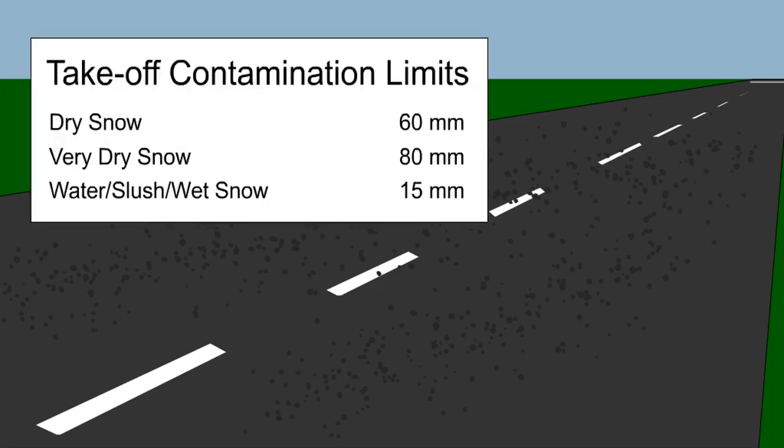A runway can be termed dry when it is not damp, wet or contaminated, the category including any paved areas which are either grooved or have a porous surface designed to give dry braking action when moisture is present. Some operations will inevitably have to take place on wet or contaminated runways, with due adjustments to landing and takeoff distances. The factors are covered fully in the performance syllabus.